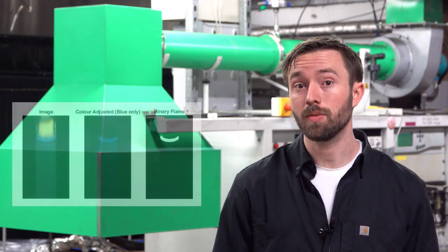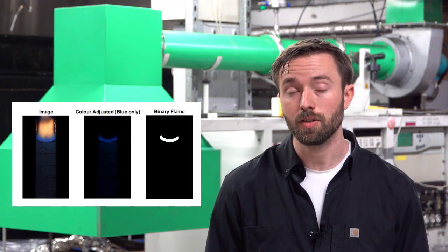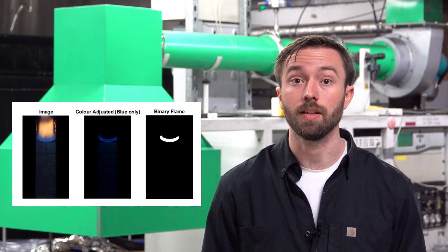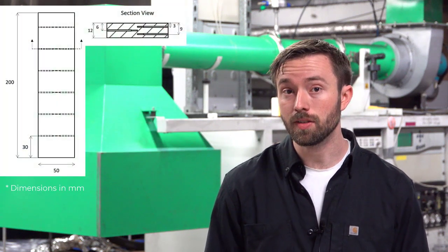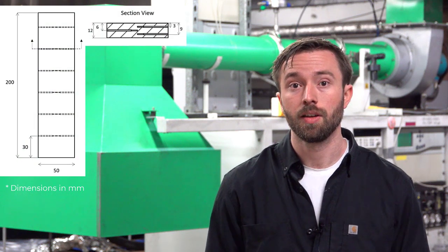In addition to changing the sample orientation and the polymer used, a series of experiments was conducted using a cone heater to apply a range of external heat fluxes at the surface. Now, this allowed us to investigate the influence of preheating on the flame spread process. Experiments were recorded, and the flame front position was determined by isolating blue pixels at the leading edge using video processing techniques, which are detailed in the paper itself. Additionally, thermocouples were placed at various depths and locations along the sample, as seen in the diagram here. Surface thermocouples were used to calculate the flame spread rate between 2 measurement locations, and these flame spread rates were then compared to the video data.